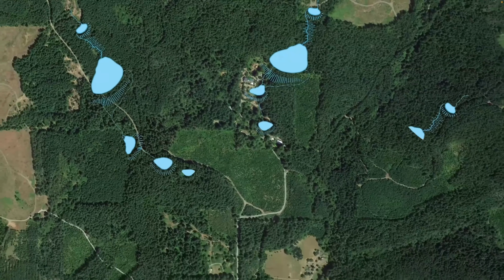Another element to consider is your inlet. On steeper ground, as you construct your pond, you can create steeper banks behind than the natural landscape condition, and in those situations you may have water seeping down or pouring down those banks. It can be really important to make sure that the backside of your pond is built to accommodate some saturation in water and won't slump after the excavation. At the inlet itself, where the water courses through, you might see an erosion gully form and a head cut, and this could be one place where that water causes erosion and leads to slumpage and accumulation of sediment in the bottom of your pond.